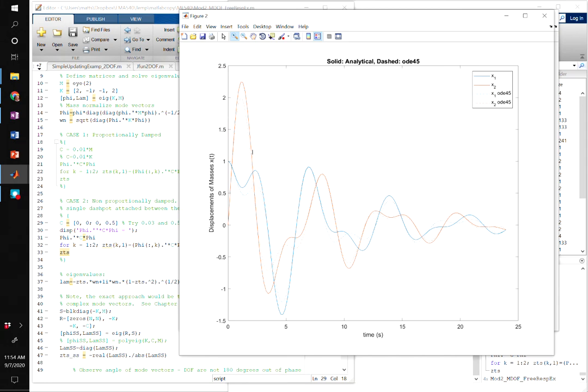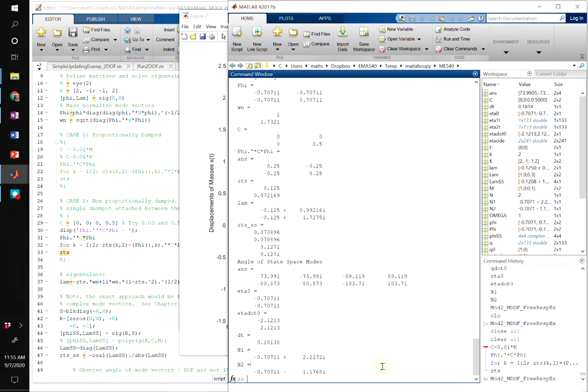And now you see there are pretty big errors that we get by using the classical diagonal modal damping assumption. We can also see that in the damping ratios. Here we're on the order of 10% damping. And if we calculate those using the true formulas, the true damping should have been a little bit different. It's not that dramatic still, but it is different.